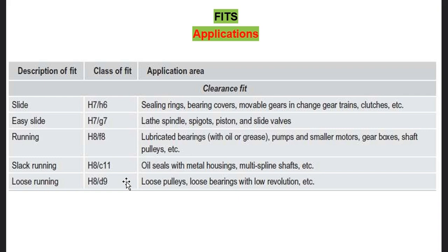Holes are generally represented by capital letters, from capital A to capital Z, let's say. That is called your fundamental deviation: capital A, capital B, capital C. And shafts are represented by small letters, from small a to small z.